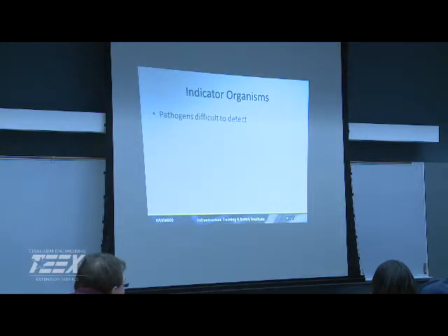Are we going to try to detect all organisms? No, too expensive, too costly, takes too long to do some of the tests. Some of them aren't easily detectable. So we're going to look at the ones that are easily detectable, right? We're going to look for our fecal contaminants, things that are coming off of our feedlots, out of our pastures, things like that. Even cross-contamination or from septic systems. If you have a septic system in close proximity to your well and you don't have good wellhead protection, now you've got a real potential source of contamination into your wells.